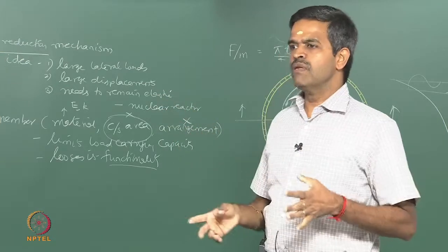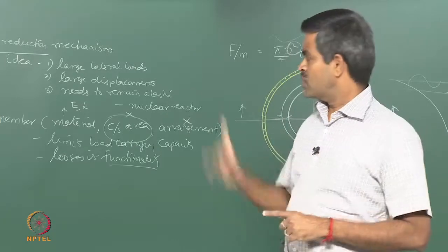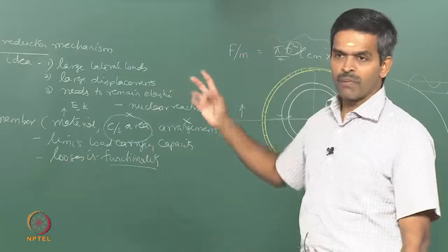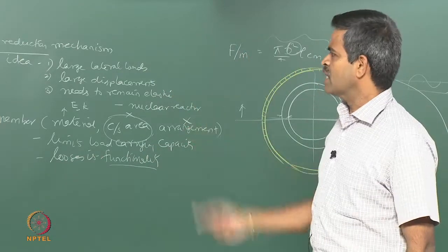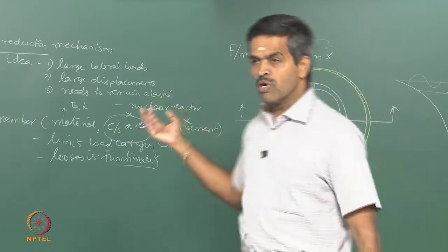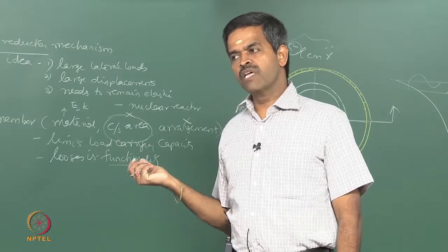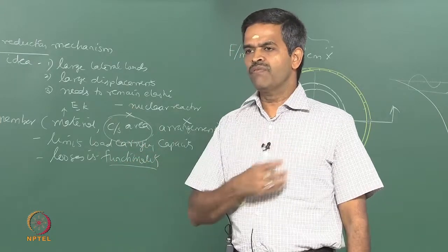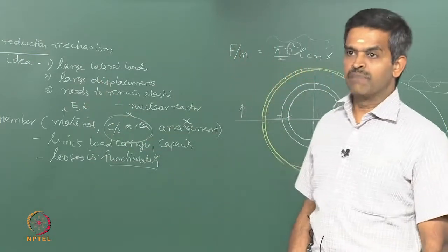It is unimaginable. You will understand, no course will advise you to design a system for this wind speed. Nobody would have designed it for this wind speed at all, because 281 km/h is a terribly high, unimaginable wind speed. That is because the hurricane came, and the wave amplitude is 24 meters. You see, the significant wave height we generally design for in offshore platforms does not exceed 15 meters for a design return period of 50 years, whereas here the amplitude is 24 meters, which is unexpected.